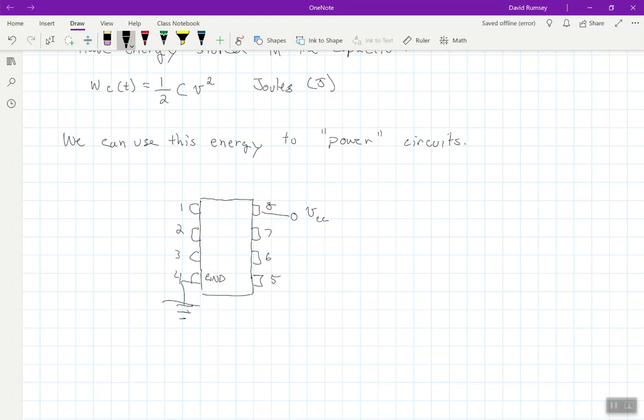And for instance, this could be an op amp. And so this is how I power the op amp up. And then I have other connections going here. But what's often done here is, having it like this is not necessarily the best thing, because if you're thinking about how a circuit board is laid out, the power supply might be all the way over here. So I have to run this all the way over to the power supply.